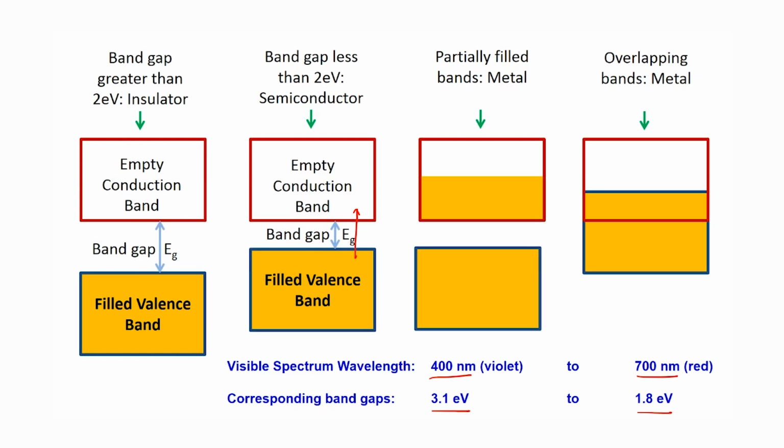So, for example, let us just use this value here, 2 electron volts. I will just assume that I have a semiconductor with a band gap of 2 electron volts, and since we have this range of radiation, I will take the 2 extremes of the radiation. I will assume that I have photons arriving on the sample which have 3.1 electron volts energy, and some other photons arriving at the sample which have 1.8 electron volts energy. So, let us say we have these options available to us.